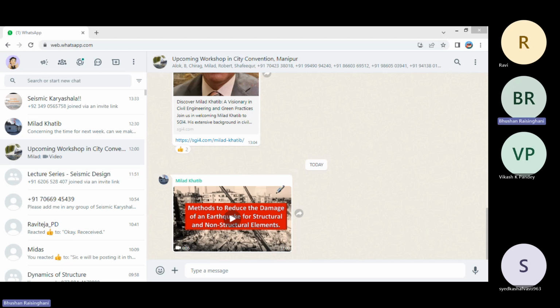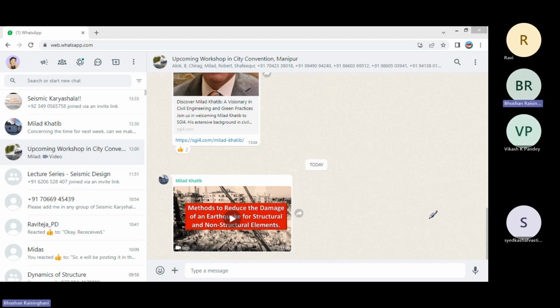If you see the diagonal, 4 bars with specially confined reinforcement have to be provided along the diagonal like this. So minimum 4 bars of 8 mm diameter.